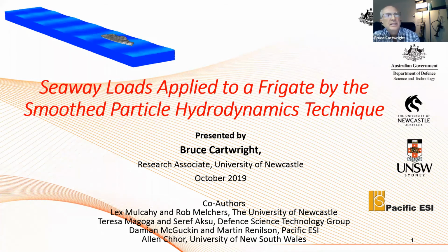We hope to be gaining access to some supercomputer time, and this will allow much greater resolution in the finite element model of the boat, so that we can actually get down to much smaller elements. At the moment, in Pacific ESI, our mesh size is still much too large to model a crack, but it's giving us really good resolution of stress distributions in areas where we are interested in what the stresses are.